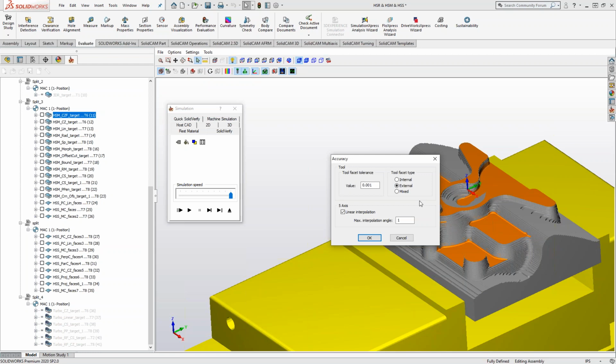It basically just goes down to this value here is the building block that we build this STL using. So there's little tiny triangles of that size. Each edge of that triangle is that length. So the tighter you make this, the smaller you make this, the more defined you can make this, more elements that get made into that STL. But you're waiting forever for that to be developed. Yep, you're waiting for that to be simulated.